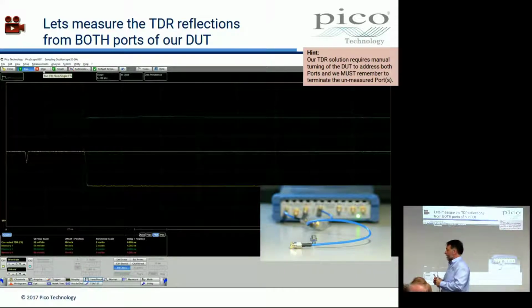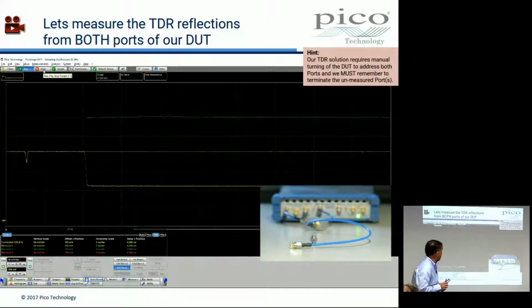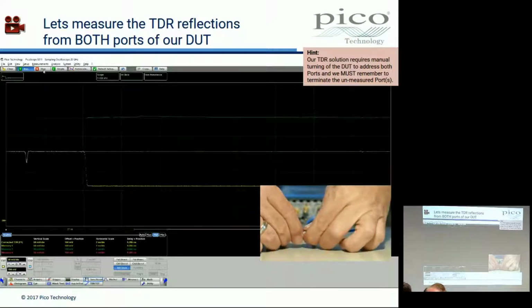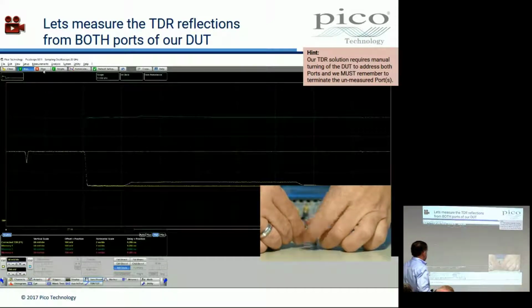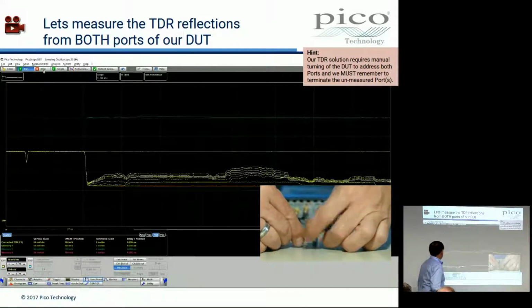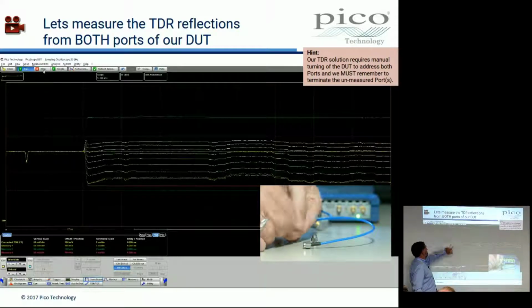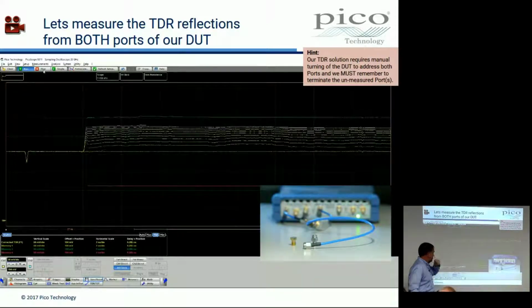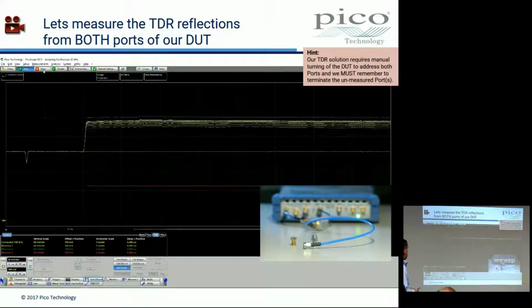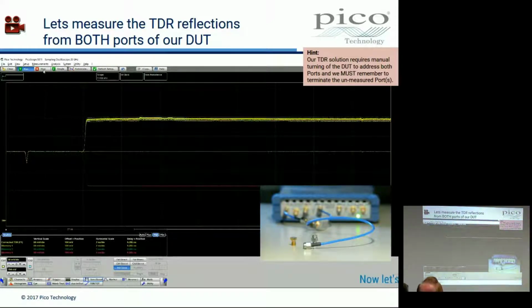So I'm going to find something out about this DUT. We take away our short circuit. We've saved short, open, load. And now we put the DUT on.